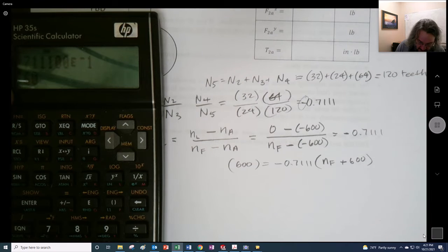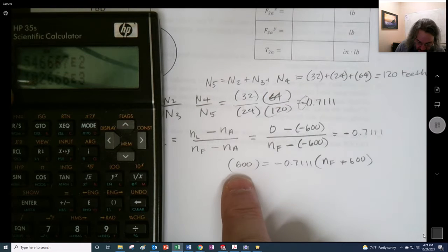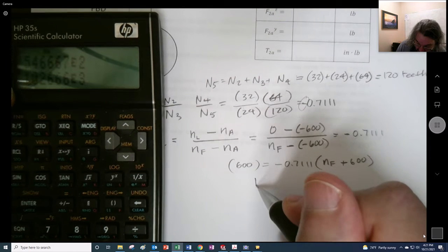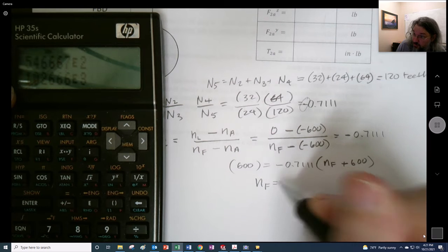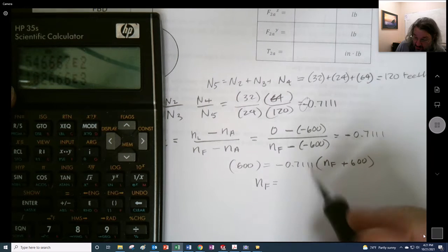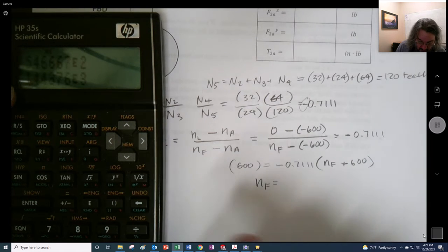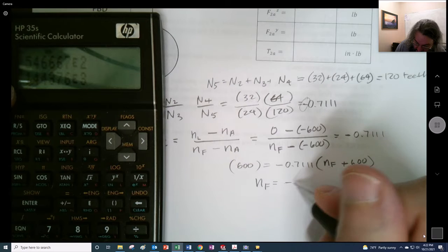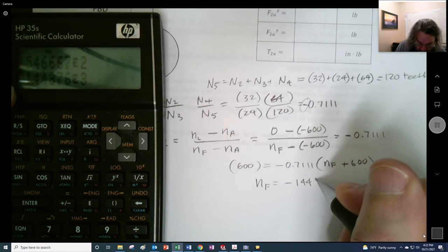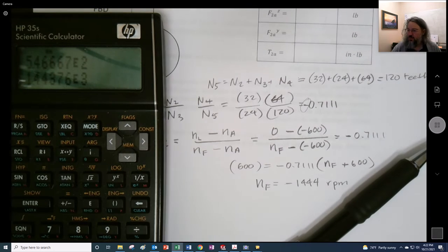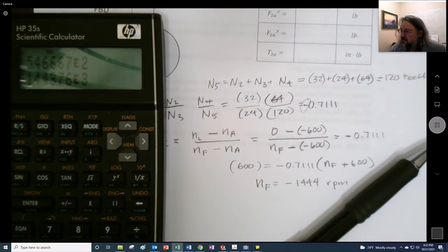It's going to be a long video. 600 times that, add it to 600, boom, we get 1026, 1027, something like that. But now we have this negative right here, so we're going to say that the direction of the first one, I think I got that correctly. We're going to divide by that 0.7111. Boom. And it ends up being negative 1,444 RPM. And I want to double, triple check all my signs as part of this right here.